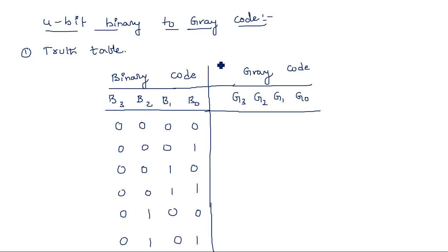Okay, now how to represent a gray code? Gray code is nothing but a mirror code. We can also call it a mirror code, or also known as a unit distance code. Gray code is the one which we are using in the K map. Every time when I say K map, I use it to say it's a gray code representation. It's a gray code format. So gray code is nothing but a unit distance code. Successive numbers must vary by a difference of only one unit distance.